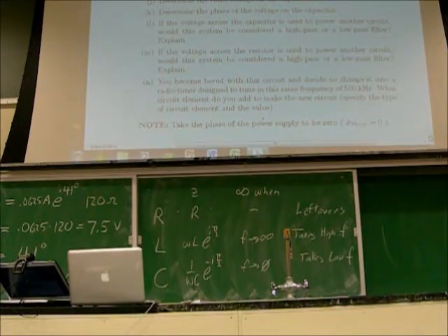So what I knew was that DC voltage is 0 frequency. So I wanted to have a low-pass filter. So I went behind the dashboard and I added a low-pass filter that I bought commercially. It wasn't strong enough, so I made it a stronger low-pass filter, and then the noise disappeared out of the radio.